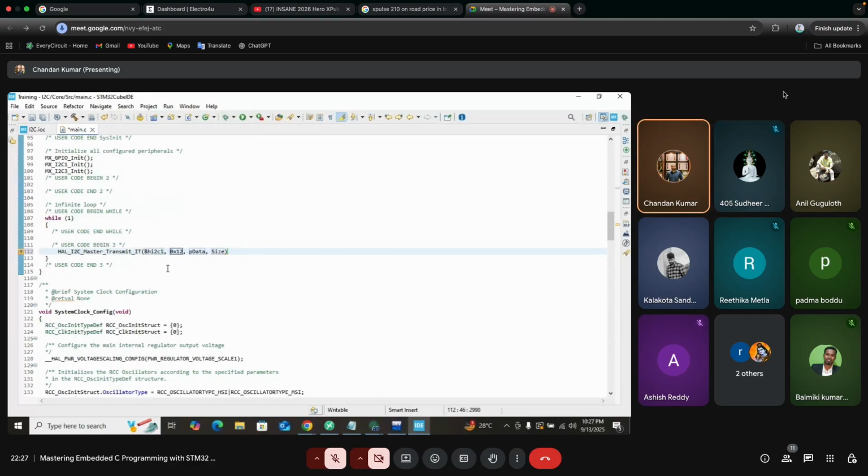Now, whenever you do register coding or anything, if you want your code to read 12, read 8, read 9, then you should just shift it by 1 bit. Here I want to transmit to the slave address 12.